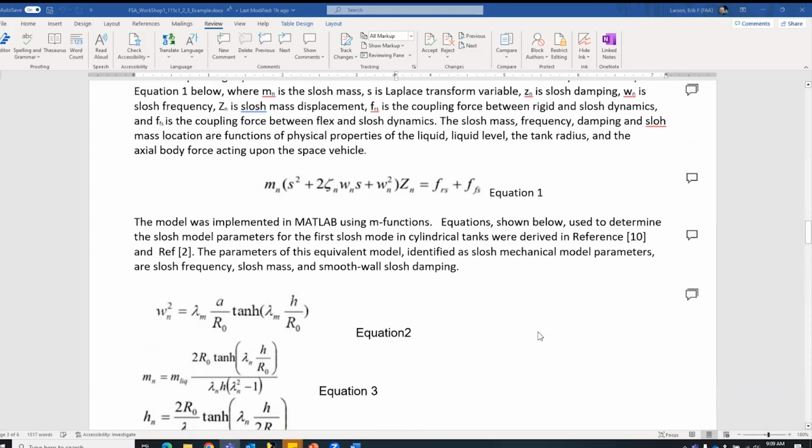And the last sentence of this paragraph, SB declares the inputs that go into the model, mainly the geometry of the tank and characteristics of the propellant, followed by a set of accepted equations and the methods of how they are implemented into the model, and the expected outputs of the model, which is the frequency, the slosh mass amount, and the location of that mass, and the damping with baffles when the liquid is excited. From these outputs, one can determine the forces and moments and add that to the six-degree-of-freedom simulation using a predefined uncertainty distribution.